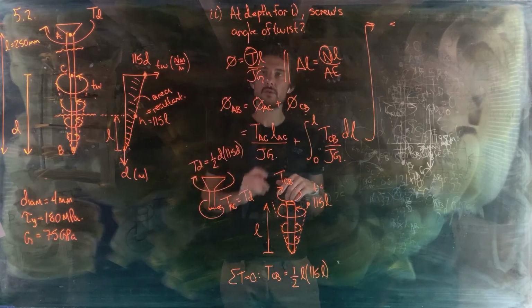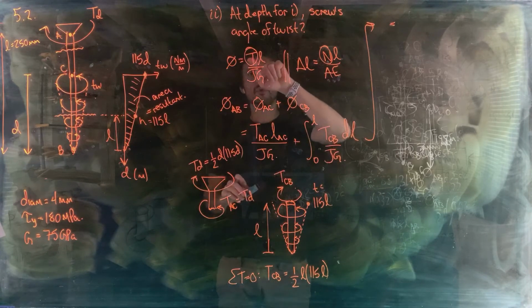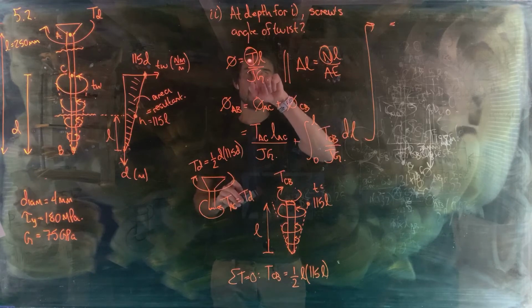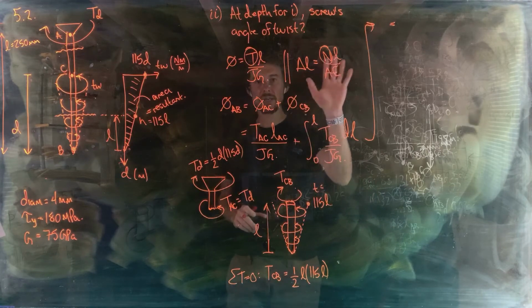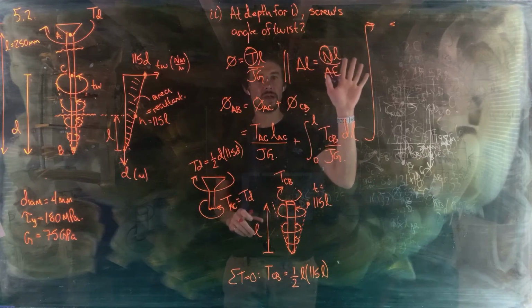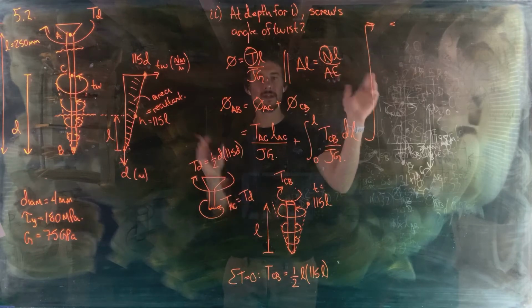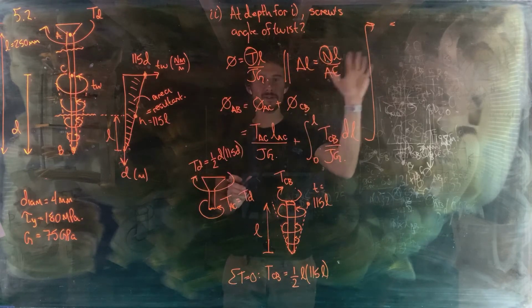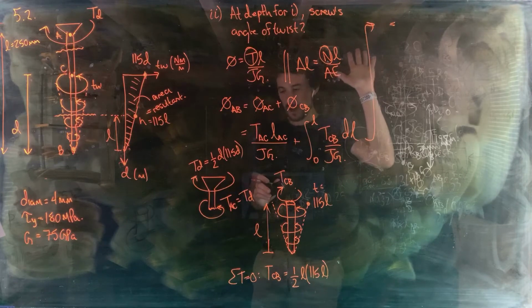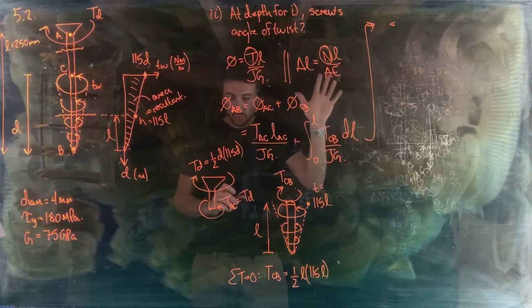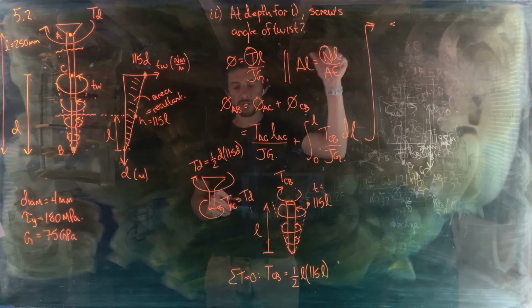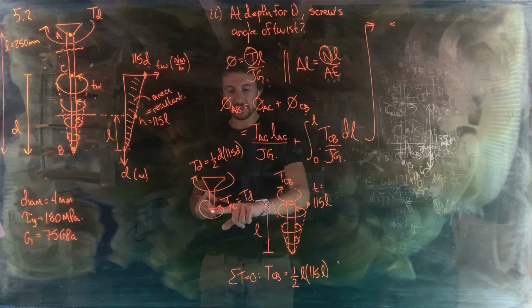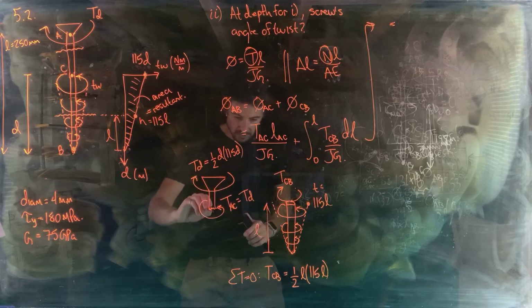For angle of twist, we do that by saying we're going to look at the sign of T by applying the right-hand rule, okay? So you take your right hand, and this is going to look to you like it's my left hand, but that's because the video is mirrored horizontally, so this is in fact my right hand. You want to take the thumb of your right hand and point it in a direction that is sticking out of the section cut that you've made.